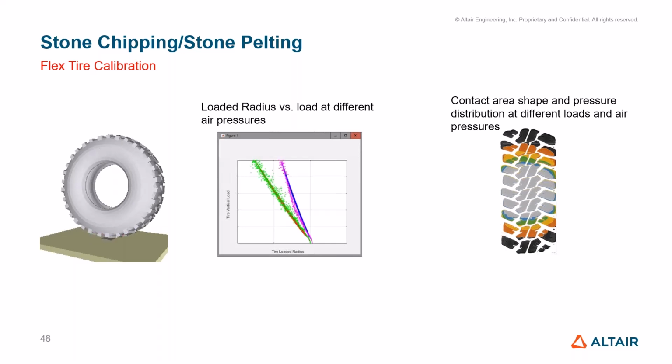If you want to use the FlexTire, you have to get loaded radius versus tire vertical load data, and you have to perform the calibration. Very soon we will be releasing how to perform the calibration, all those details, in the Altair community forum.